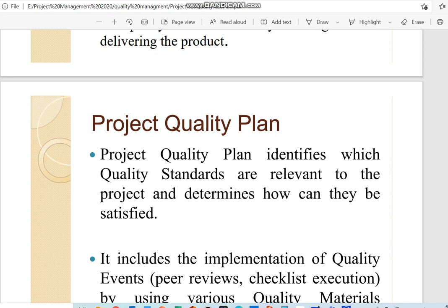You can go to some very nitty-gritty detail, but actually it may not be necessary. So it's actually good to get the perspective of the builder to come in. So when you start the project, after the confirmation of the contractor, if it's just traditional general contracting, then we will get the feedback from the contractor to sit down and work on the PQP. But if it's a design and build project, you can do it a lot earlier. During the design stage, you can start to get the PQP already, at the same time as you are thinking about how to construct it.